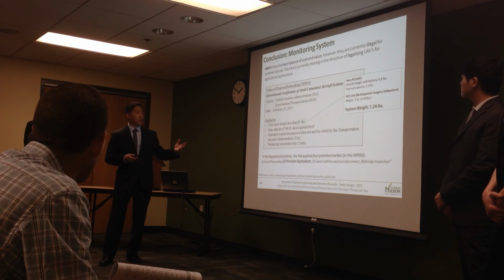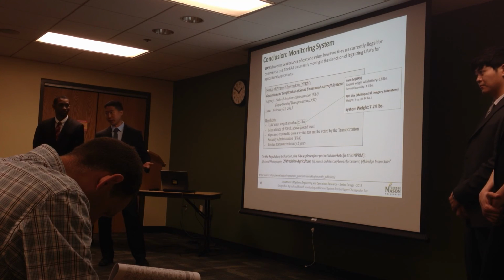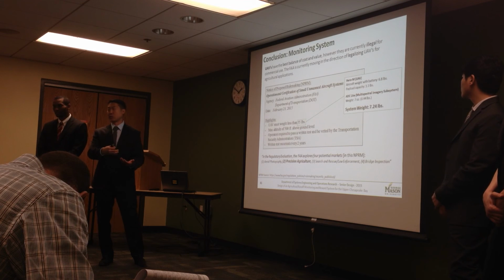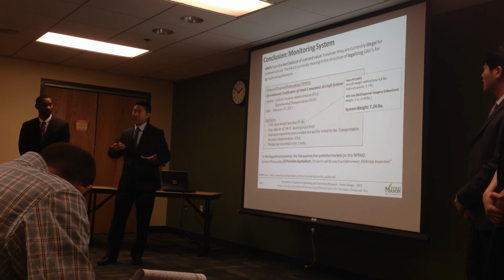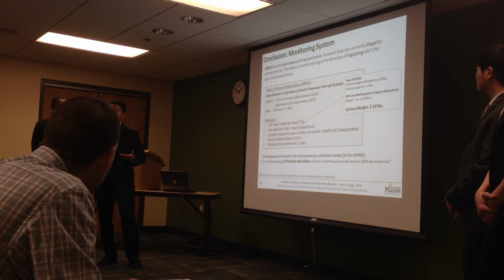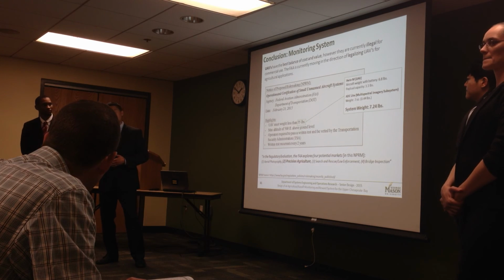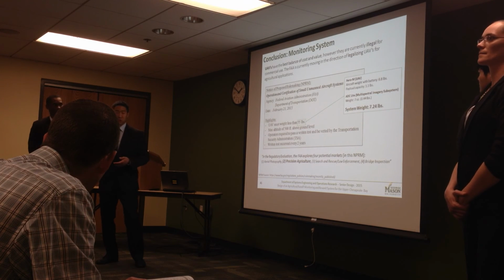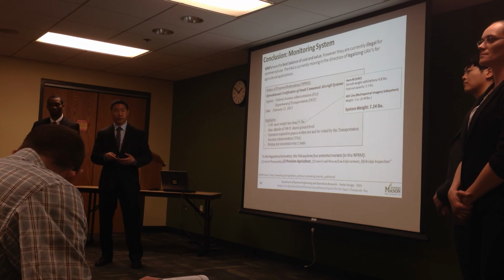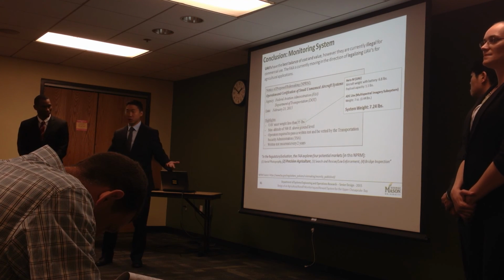And some of the highlights from this include that UAVs could fly at a max altitude of 500 feet above ground level. And they do want the operators to pass a written test, which still is not as extensive a process as becoming a licensed pilot, and that the UAVs must weigh less than 55 pounds. Now, the UAV system that we used in this analysis, with the multispectral imagery system, would weigh under 7.5 pounds. And also noting the NPRM, they look at 4 major markets in terms of potential markets, one of which is agriculture.